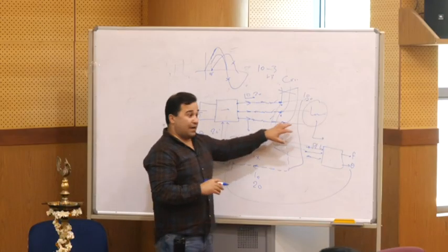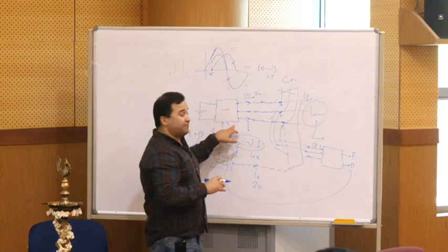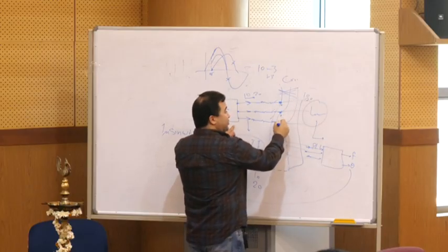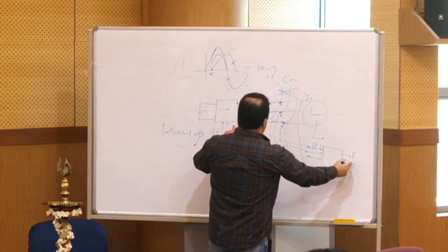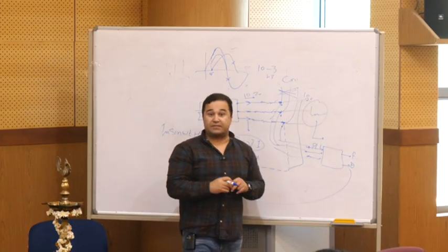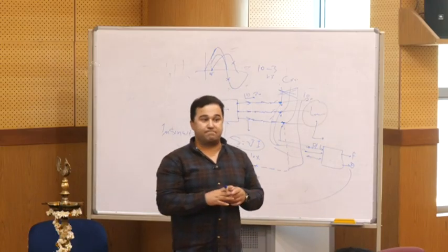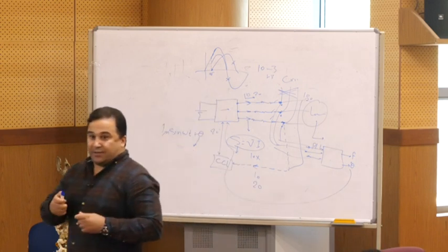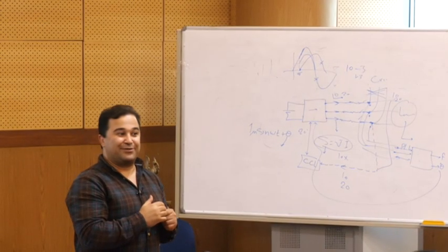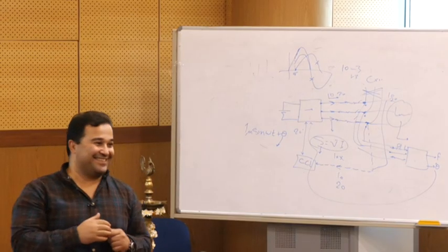So if this happens, it means that when you have this converter and the grid goes to outage, we have no reference for the PLL, and then the PLL gives 0, and then it shuts down. This is the problem. They have some solution for that one. We will see later. Okay, good. So is it clear, 100%?